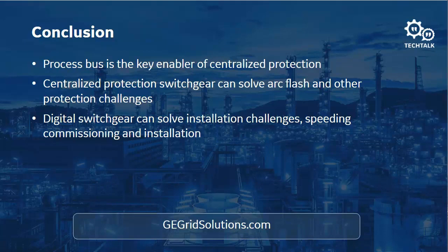Another issue is if I want to maintain my ring or repair my ring. If I have a breaker section out for maintenance, it fails, whatever, and an MU320 is out, if I want to restore my ring, I have to plug each one of those. I have to have a female-to-female connector to plug the two fibers into. So it costs me a little bit of labor costs. So those are sort of the reasons I don't like the HSR ring. If I'm going to use a network, I would prefer to use a switched Ethernet process bus.